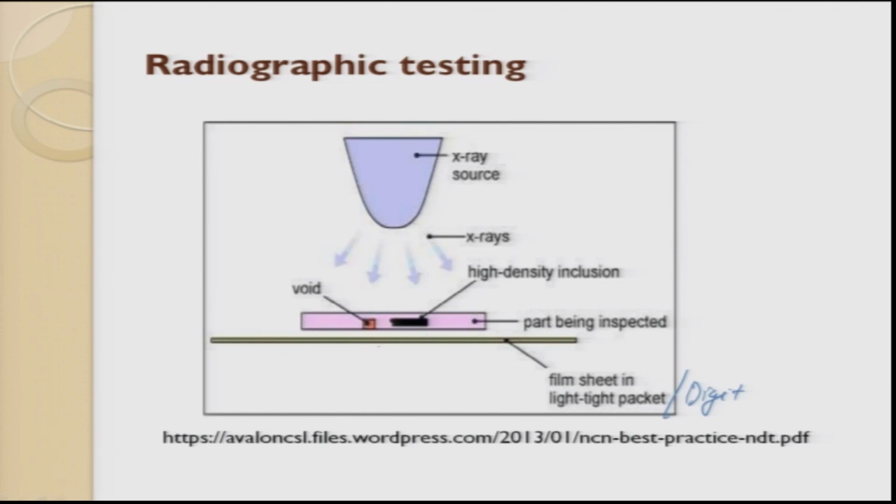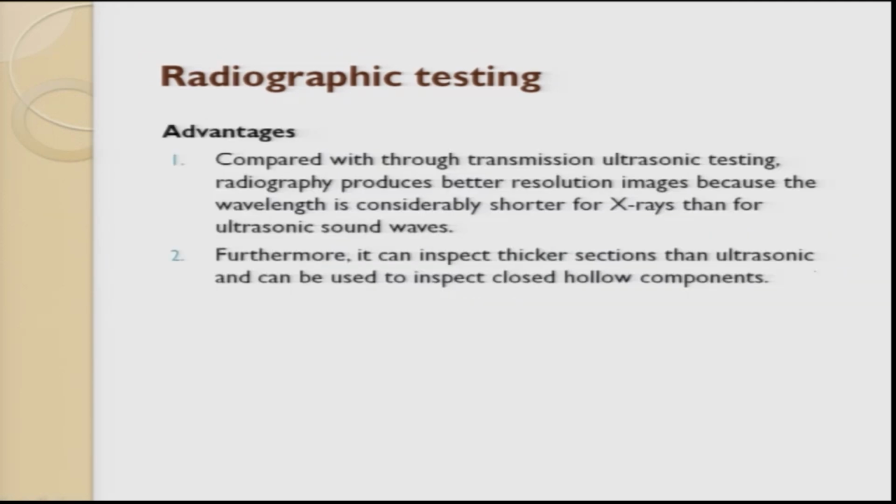Suppose there are defects like this. These two defects will not be found, because there is nothing that reflects back. And second, if this defect is very large, all these small defects can be nullified. And if this crack grows in a 3-dimensional plane, then also it is very difficult to use the radiography technique to get results.